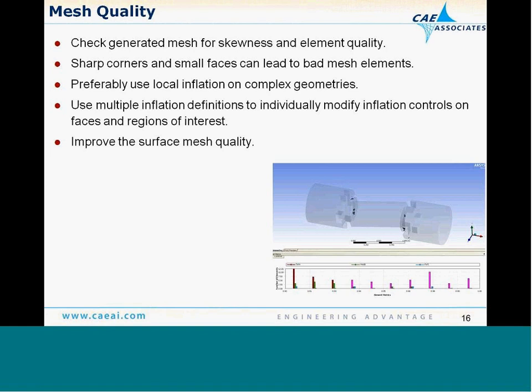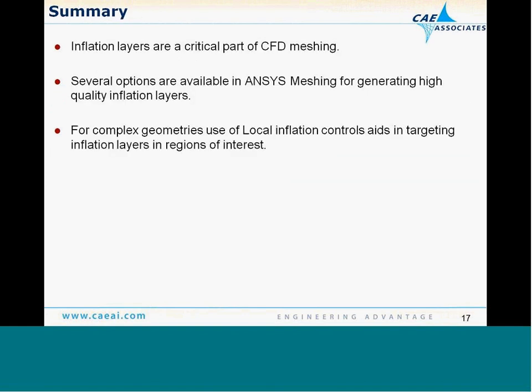So finally, in summary, we have talked about how important the inflation layers are for CFD applications. There are several options which are available in ANSYS meshing for generating these high fidelity inflation layers. And if you have complex geometries, preferably use local inflation controls because it will definitely help you in getting rid of those highly skewed meshes.